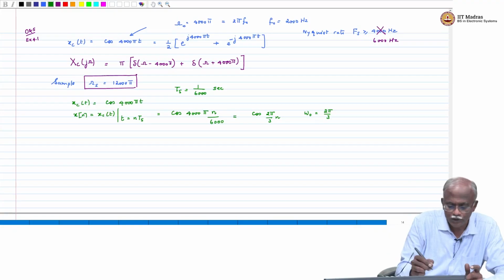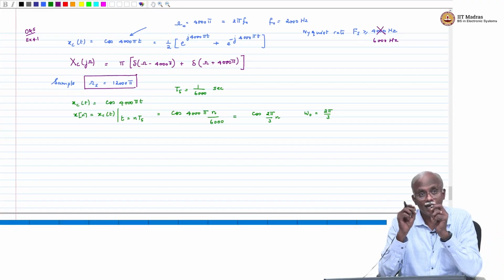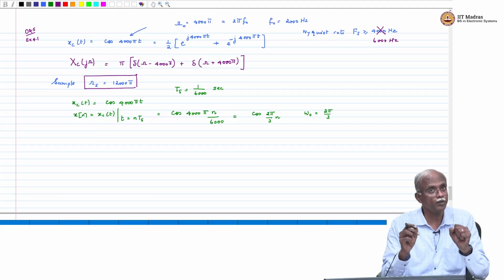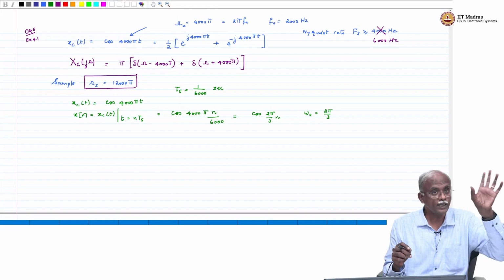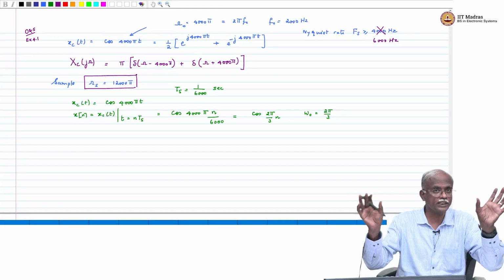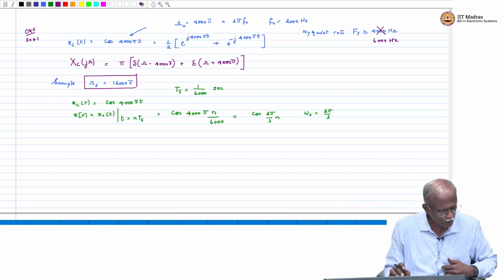Now I also want you to take this opportunity to study the sampling process. That is very important. So in the sampling process, you started out with two delta functions, one at 4,000 pi and another one at minus 4,000 pi.